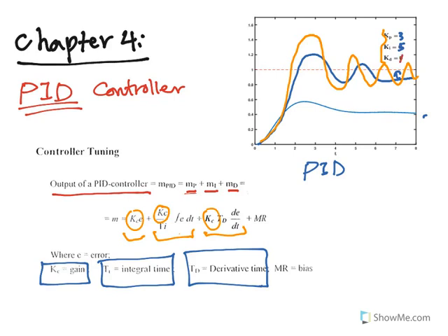For the derivative, normally the gain is very small, like 0.3, 0.2 or something like that. So normally the response will be fast, and the oscillation will be less. There is no overshoot, and it should reach the set point. The process variable should reach the set point within the minimum settling time. So this will give you the overview of how these controllers can be combined and what their effect or impact is on the output of the controller and the process variable at the end.